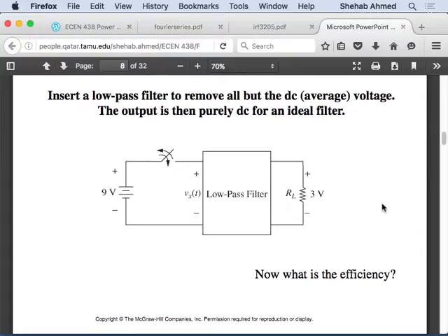So anyway, that's what we have inside this filter. This filter will affect power loss. So you will design this filter with different capacitor and inductor technology. This will affect power loss, and you will take a hit based on the quality of the capacitor and the quality of the inductor that you have. But you're not limited only by the quality that you have. You're limited by the application.